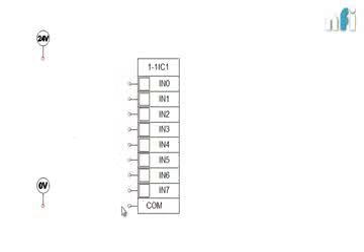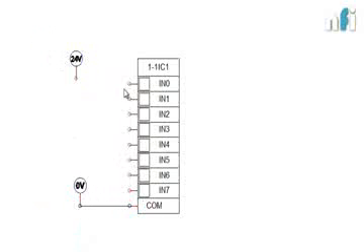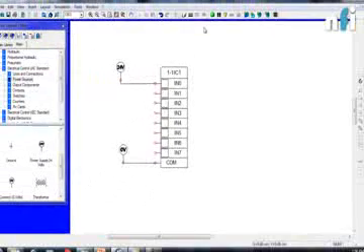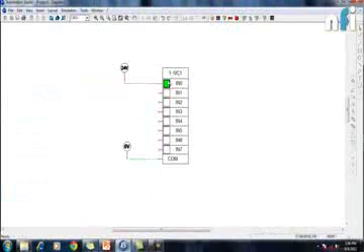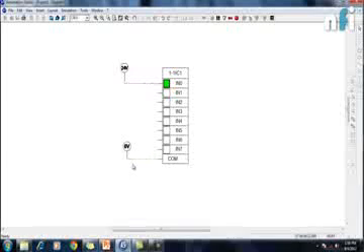You can see a common terminal here. Now I am going to connect this 0 volt to this common, like this. So my 0 volt has been connected to common. Now you have to understand that we need to create a potential difference of 24 volt across these input terminals. Then only will this PLC recognize that there is some input. For example, if I connect this 24 over here and simulate, you will see this is on. This is on because of this 24 volt and the 0 volt, which is connected internally to this input. So we have created a potential difference of 24 volt.